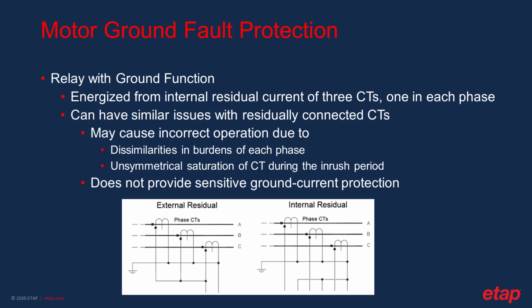These errors are caused by dissimilarities in burdens of each phase and unsymmetrical saturation for each type of CT, even if they are same model, same type. So you cannot guarantee that they are ideally the same. This type of connection typically cannot provide the sensitive ground fault protection of the motor.